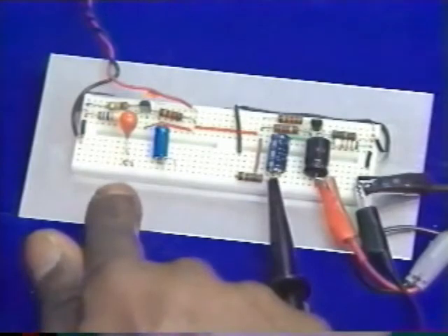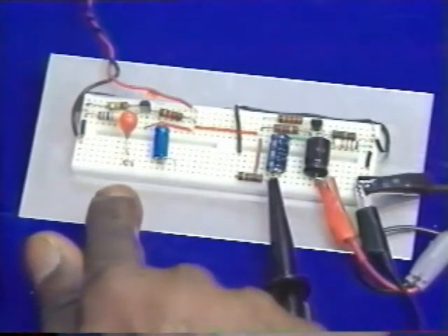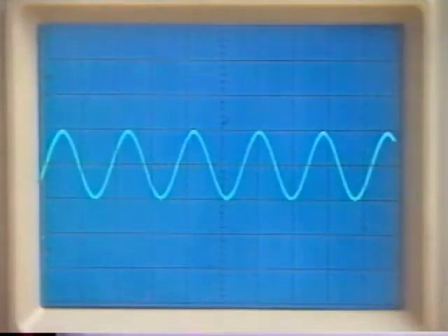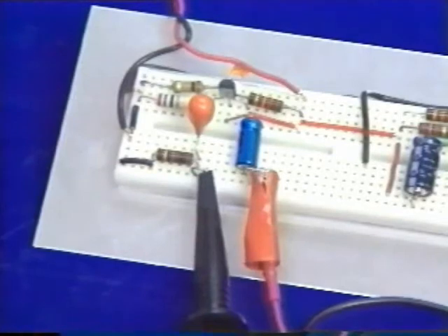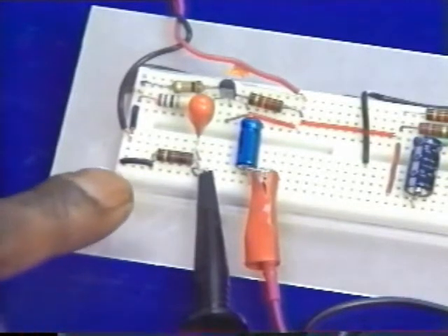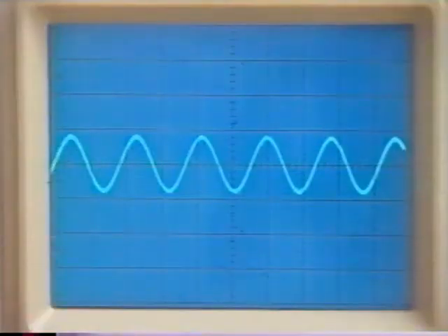Now let's look at the amplifier on the left with the low output resistance. Here, with only the oscilloscope connected, there is also an output voltage of 1 volt peak to peak. When the 100 ohm load resistor is connected to this amplifier, the output voltage changes only slightly. This means that in order for an amp to drive a low resistance load, it must have a very low value of Rout.